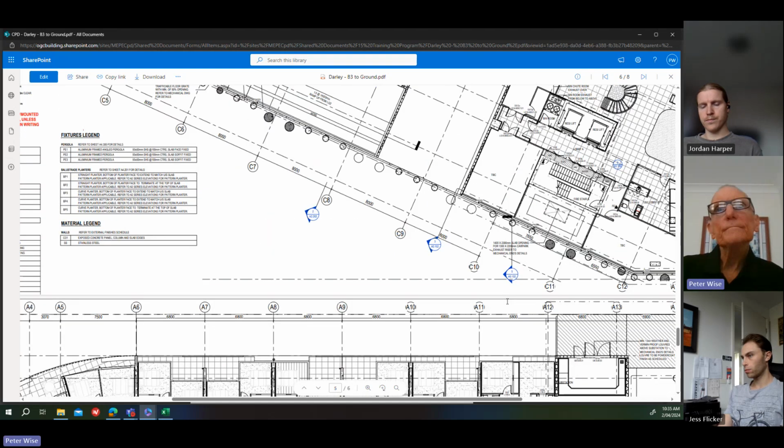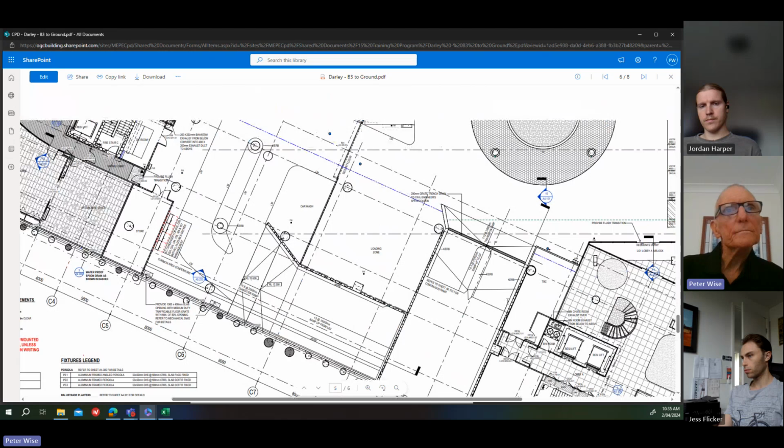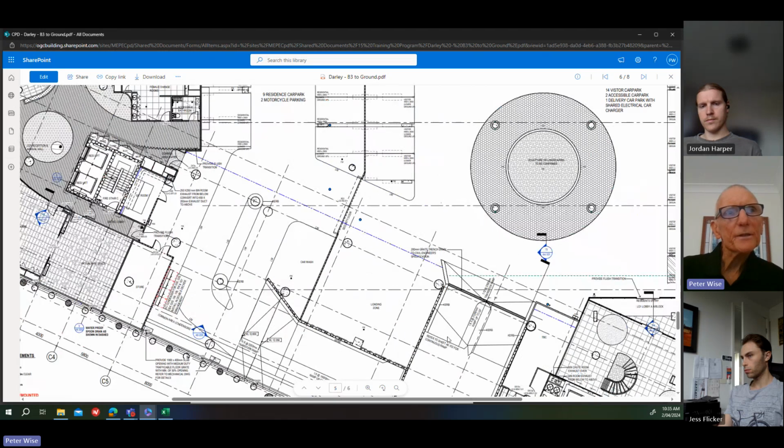And then I've also said, have a look on the drawings just quickly and see if you can see where the mechanical supply air, makeup air, is going down through the building, because there should be makeup going into each level, supply air into each level. Just as you've got supply air coming in, exhaust air coming out on each level.